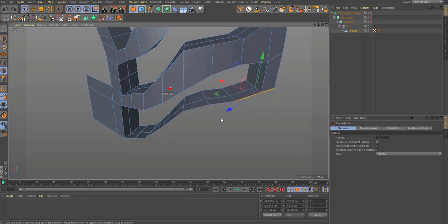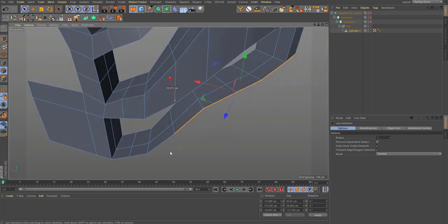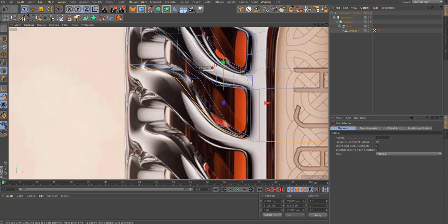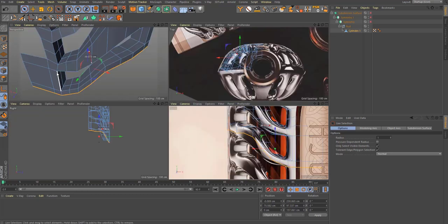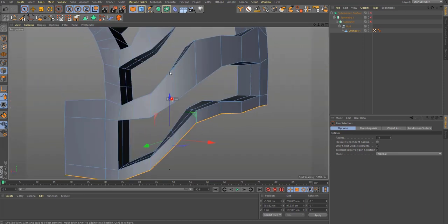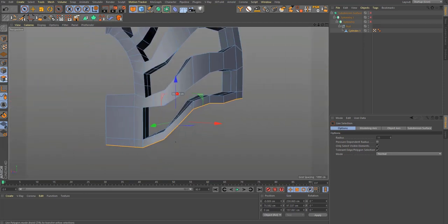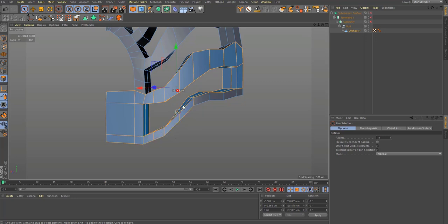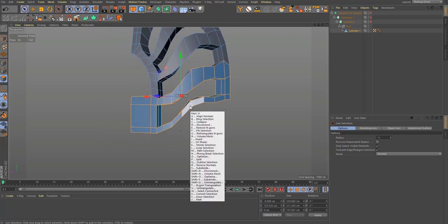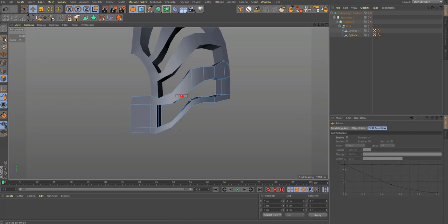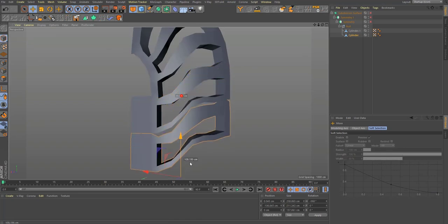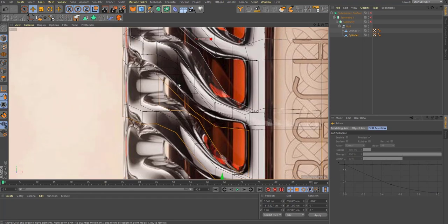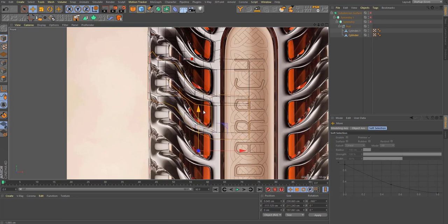So, actually, let me just add, because this part is gonna give me a headache too. I'm just gonna add these points, kind of like this. Okay? Yeah. So now again, we're gonna select the polygons. We're gonna press UP, and now we're just gonna move this down where we think the next model is gonna be.